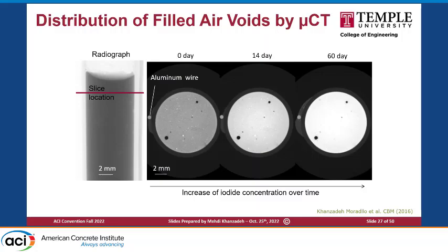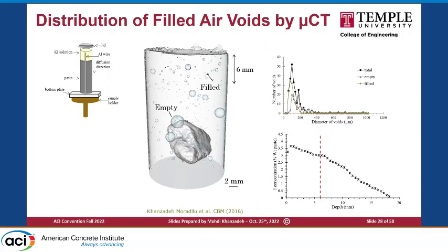So this is a paste sample at the left side. We took a radiograph at different angles, then we reconstructed and took these images. As you can see here at the left side, we have the control one, and then over time we can monitor and quantify which size of the air voids and what percentage of the air voids are getting filled with this salt deposit or salt solution.